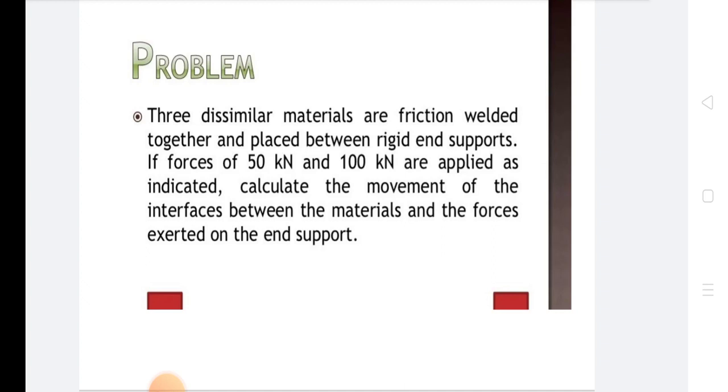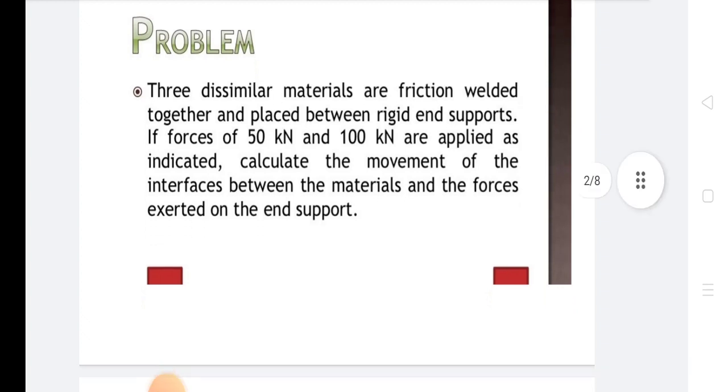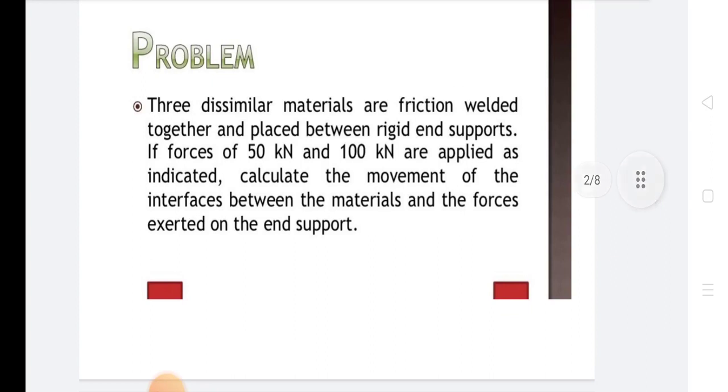In step 2, selection of displacement model. For the continuum discretized into a number of small elements, the displacement variation over each element is unknown. Hence, a displacement function is required to be assumed for each of these elements, known as the displacement model. There are two kinds of displacement function that could be assumed: polynomial displacement function and trigonometric displacement function.